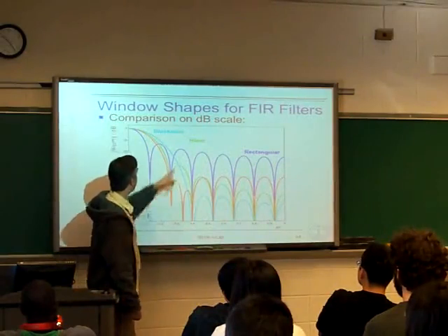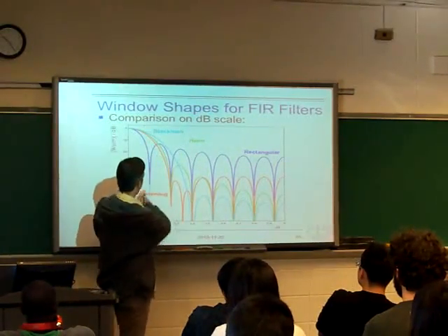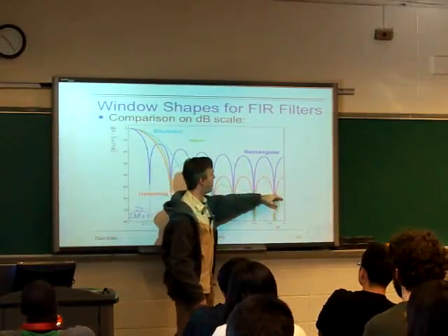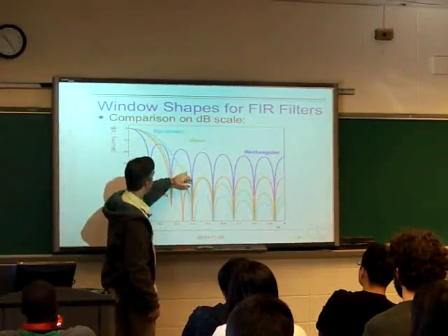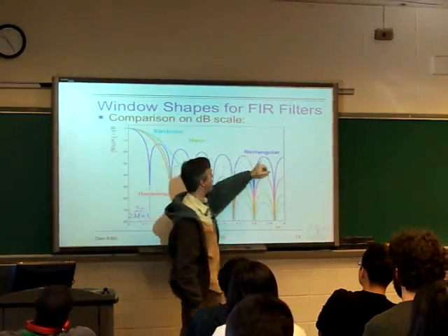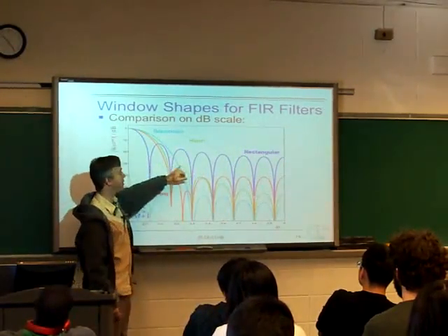The Hann window was the one where we just had the raised cosine, and so now the first lobe is twice as far out, and we see these things die away nicely with frequency, right? And the first one is much lower than even any of the rectangular window lobes, but it's still quite high. It's like minus 32 dB or something here.